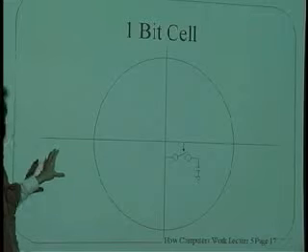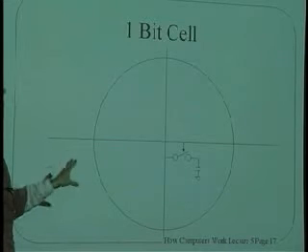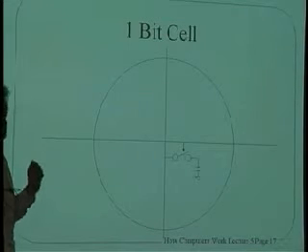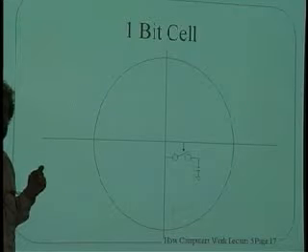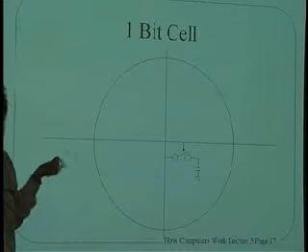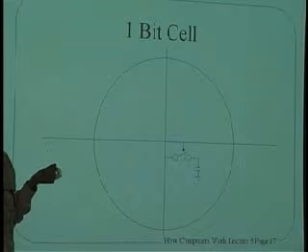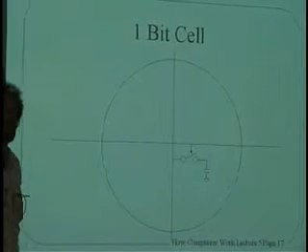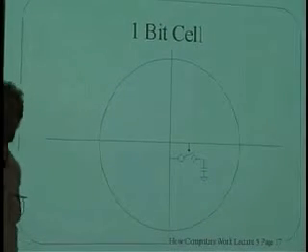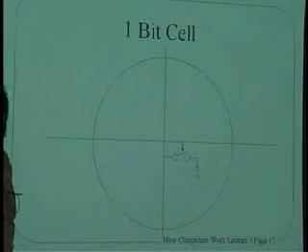And in fact, this is called DRAM, the D of dynamic random access memory. The D means that it is dynamic, meaning that I cannot depend on it statically to hold charge. Now, how do I actually deal with the fact that it's leaking all the time? What if I actually wanted to use my bathtub as storage?